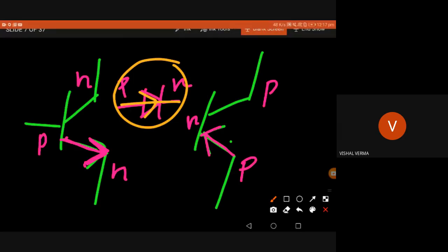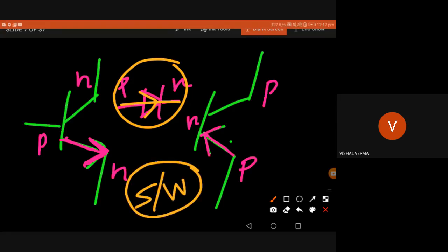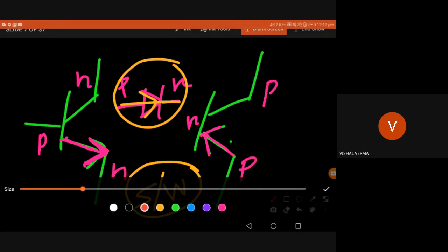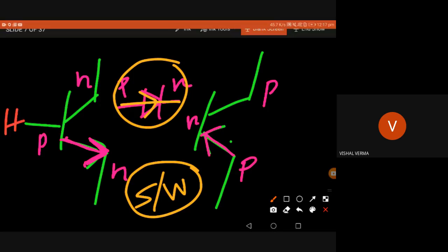Now, for operating a transistor as a switch, whenever we discuss a transistor switch, we are in a digital world. Digital world means high and low, 1 and 0, binary. It makes our life so easy. So in abstraction, when we assume the transistor operating as a switch, I'll assume the same operation for NPN and PNP transistors. For an NPN transistor, if my input is high, which should actually be current rather than voltage, but whatever, if a high signal is given to the base or control terminal, my NPN transistor is on. That means my collector and emitter are short circuited, or have some low resistance.